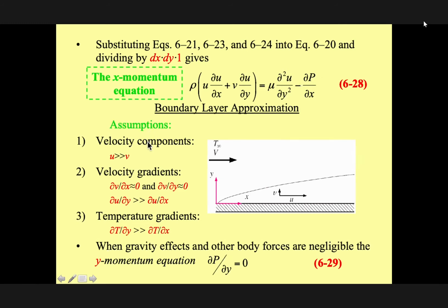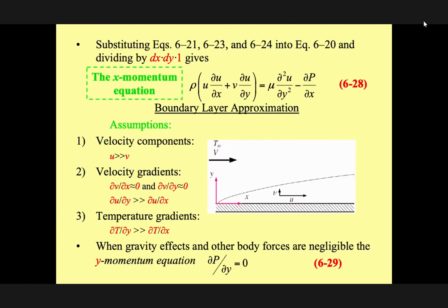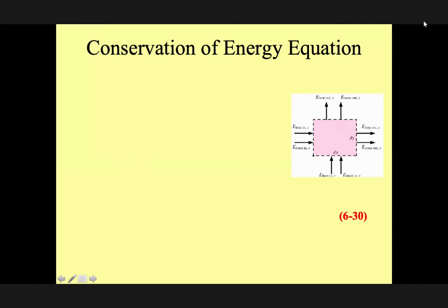Therefore, we make some assumptions to simplify this term, okay? If you look here, we also had dp over dy, okay? But we are trying to ignore it, because in this direction the pressure drop compared to x is almost negligible. Therefore, we make a number of assumptions to end up with the equation we end up with here, okay? Again, every time we move through the equation, we try to find which term is dominating. We keep the terms that are important, but we can ignore the other terms that we mentioned here.